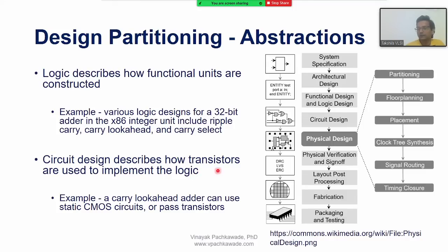As I explained to you earlier, if you want to design a multiplexer, or let's say an inverter, you can use the compound gate logic approach, and you can use the tri-state logic approach. For the multiplexer you can use the compound gate way, because you know how to use the pull-up network and pull-down network using transistors, or the multiplexer can be built with tri-state logic, or with pass gate logic.